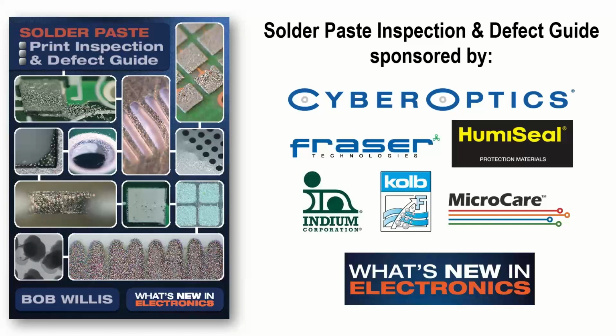What cleaning method is the best? Stencil cleaning, ultrasonic or manual cleaning? Okay, I have not found at this moment in time, ultrasonic cleaning to affect the cleaning of stencils. Now, I've done it manually, as you've seen on the video, and during that particular exhibition, I was cleaning this stencil. And I really didn't see any impact on it.